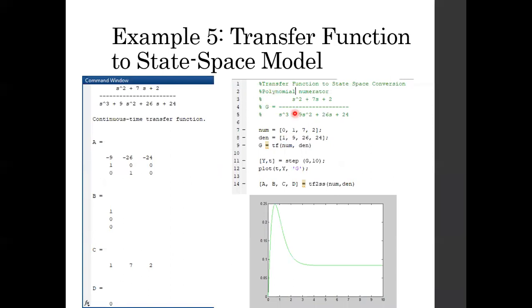So again, this is our MATLAB script for converting our transfer function. So same script. We define the numerator and then we define the denominator. Okay, so same command or instruction we used here. And so here is our transfer function, and it still gives the same matrix A as in example 4, and same matrix B as in example 4.